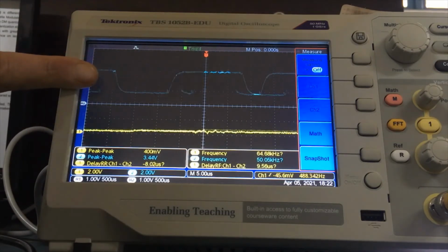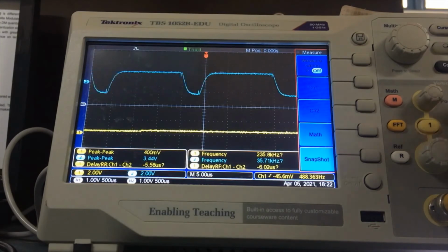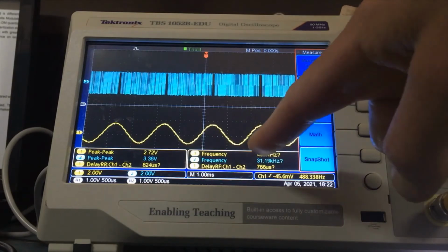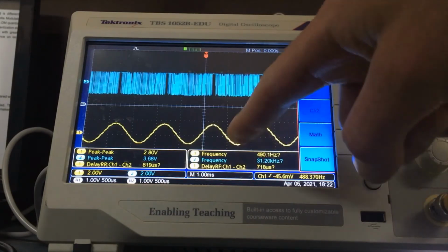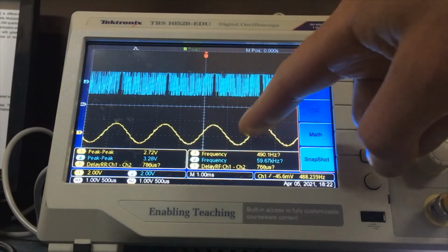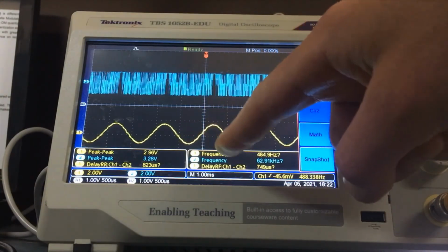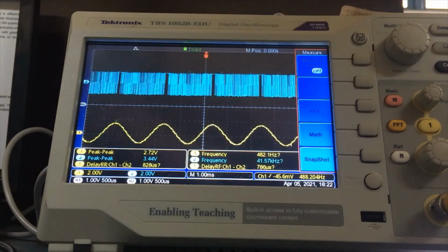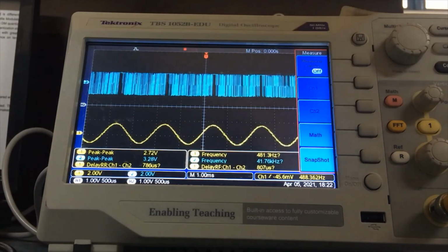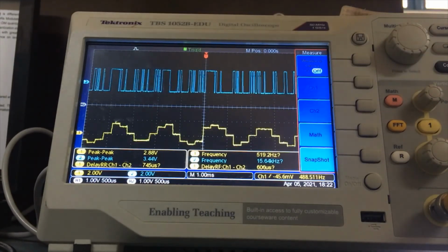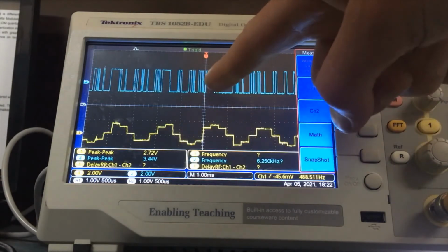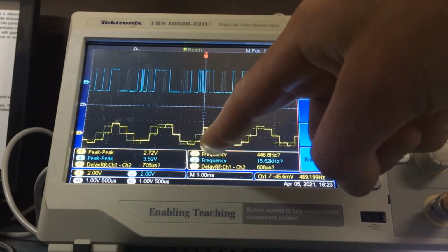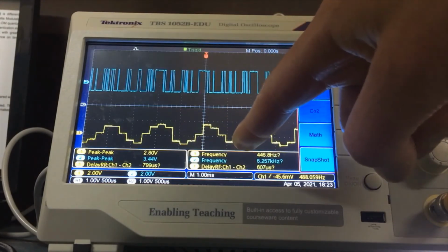Because the sampling frequency is very high, we need to reduce the scope so that we can see the changes. So here you are, this is the transmitted signal at very high sampling. That's why it is looking continuous. And this is our PCM signal. If we change the sampling frequency, reduce it to, let's say, 4, you can see right here that the sampling periods are clearly visible over here, which are almost 8.